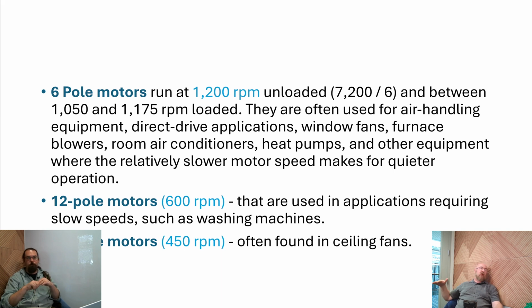The more poles we have, the less vibration and noise they generate, which is an additional benefit. A ceiling fan doesn't need a lot of torque, but we're still utilizing a 16-pole motor because it is very quiet.